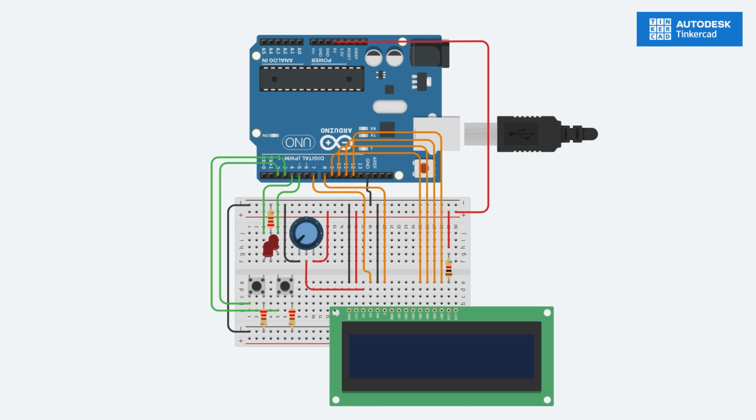After this, we'll connect the anode and the cathode, which are the backlight. So we'll connect the first, the anode, to the 5-volt connection, and we'll connect the second, the cathode port, to our ground. And once this is done, the code will work. The setup is done. The setup of the Arduino has been completed.